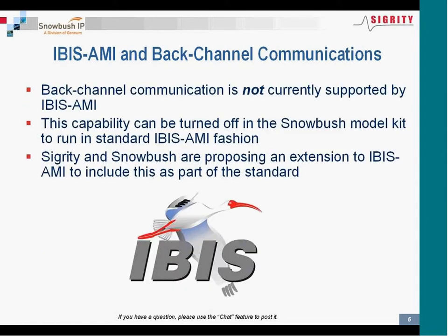IBIS AMI does not currently support back-channel communications. This capability in the Snowbush model kit can be turned on or off. If you turn it off, it will run in standard IBIS AMI mode. You can go in and set coefficients and settings in the models and run them in any IBIS AMI compliant